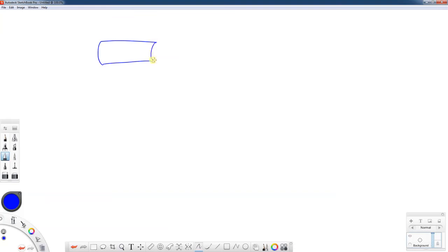So right now I have this pipe and it's all fixed on this edge, and it's over constrained. Really what we would like to do is, if we're pulling on this pipe, we need to have it constrained in our Z direction, which is down the axis. But we want it to freely contract in the radial direction.